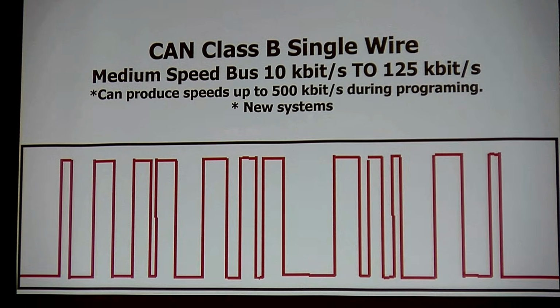And I failed to mention that in CAN, there's a new CAN that's FD. It's flexible data, and it's used on the same bus. So you remember how we were talking about having an 11-bit identifier and a 29-bit identifier? Those two frames of data are being used on the same line. Those aren't different. Like, I don't have one system that does 29 and one that does 11. The 11 and 29 are on the same system. They're both communicating and they're both sending different messages at the same time.